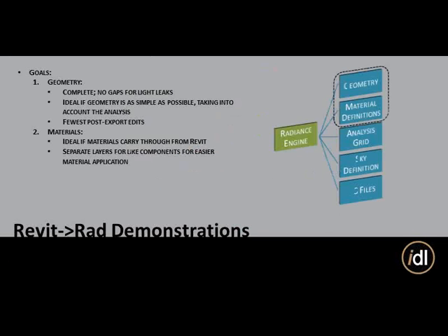So thank you, Jake. First of all, I just want to be clear on what exactly we're looking at and what we're trying to get out of the Revit model. Radiance uses various different input file types. There's stuff you can input to define the grid, different sky definitions, time, date, and there are IES files as well that you can put in if required. But Revit itself is just going to export and give us the geometry and possibly the material definition. So that's what we are focused on right now, and what we're trying to define within this little demo.